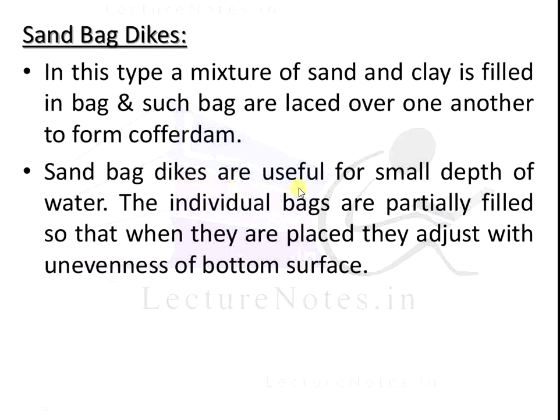The sandbag dikes are useful for small depths of water. This type of cofferdam is useful when a small depth of water is present. The individual bags are partially filled so that when they are placed, they adjust to the unevenness of the bottom surface.